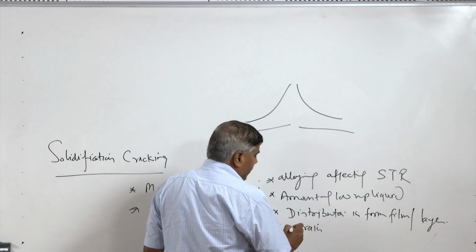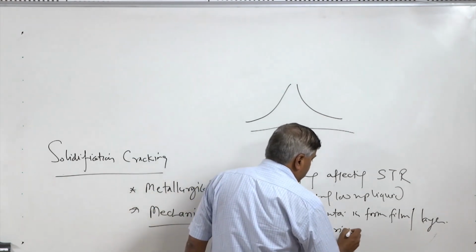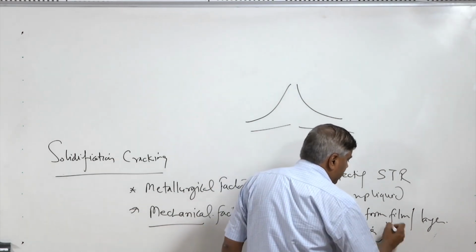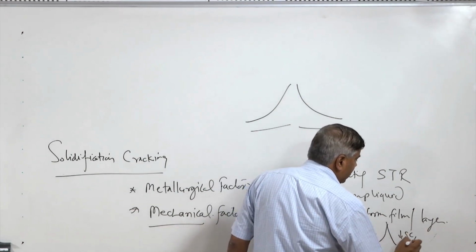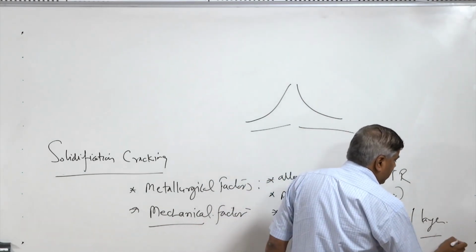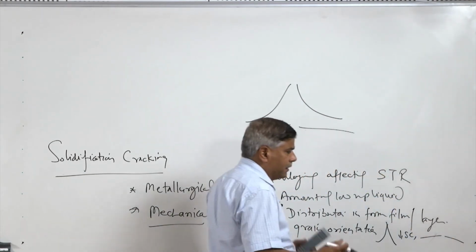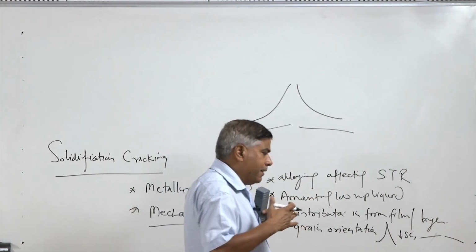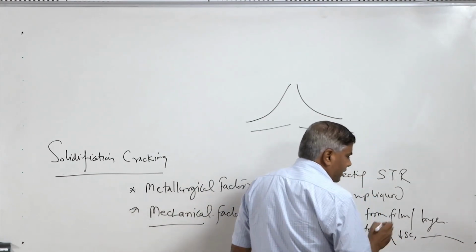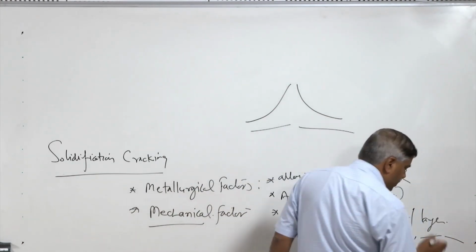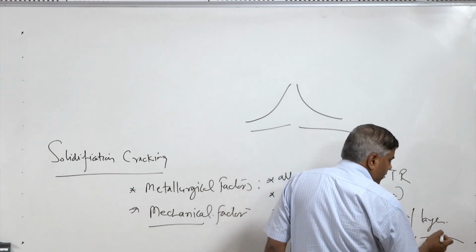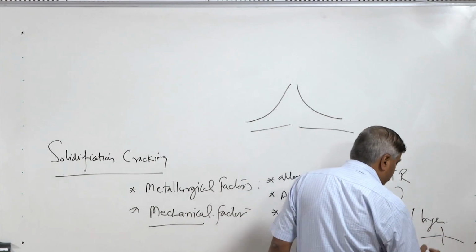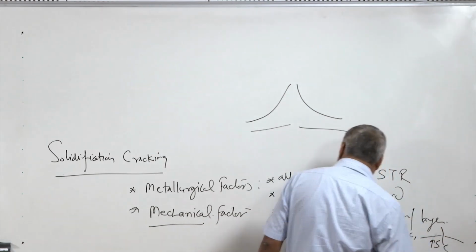So the grain orientation is one of the factors. The curved grains lower the solidification cracking, while the abutting high-angle grains, growing perpendicular to the fusion boundary and abutting at a high angle at the center, promote the concentration of the alloying element at the center line, and so they promote the solidification cracking.